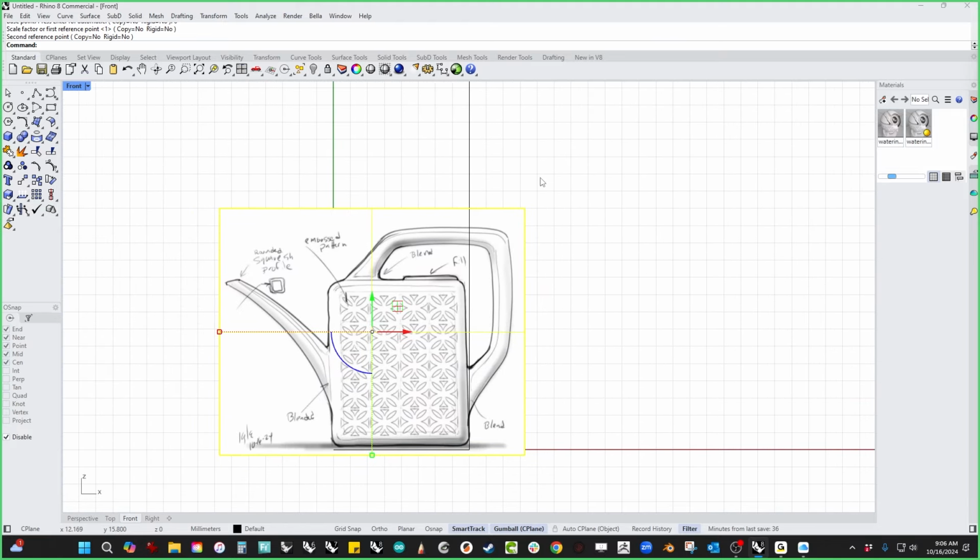If you had to do something that was super precise, you would want to take the photos or the sketch or anything like that, and put some kind of scale in the image so that you could scale this once you got in here. So you'd want a 1 inch by 1 inch square on the sketch, or 10 millimeter by 10 millimeter, whatever you want to do, something that you can scale to specifically. But in this case, just something vague is kind of where we're aiming for. And if we throw a linear dimension on here, it should be in the vague neighborhood of 8-ish, which is fine. So we'll just go ahead and go with that.